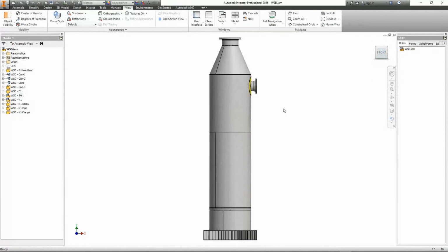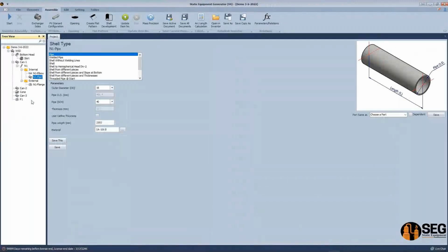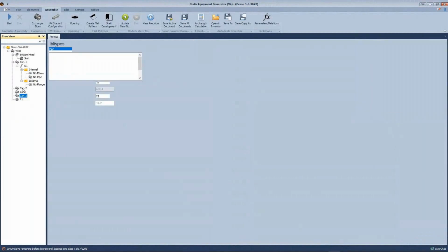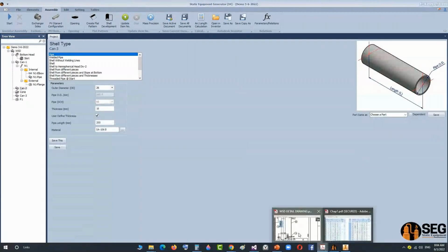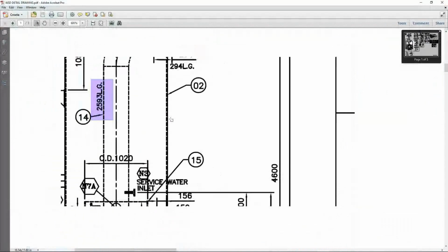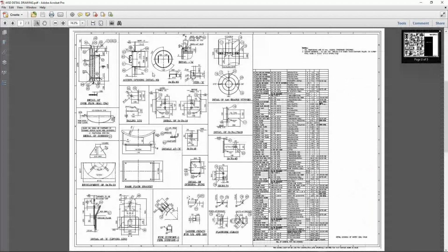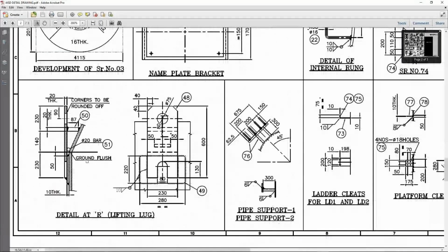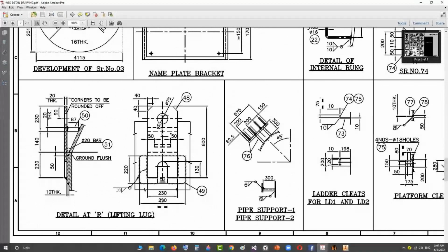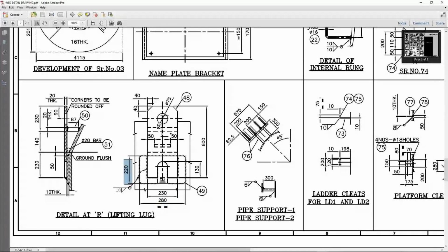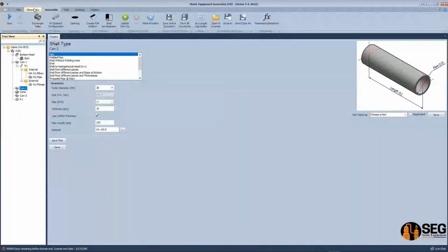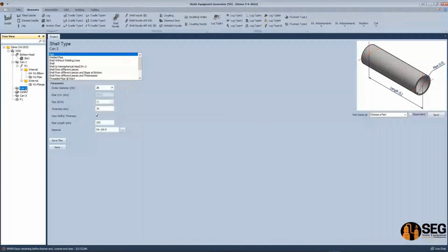Okay, now let's add a lifting lug to this can. So if we come back here, we have lifting lugs, and let's check the detail of the lifting lugs. Here we have this lifting lug. Okay, so that's the width and height. From elements here, let's select the can first, and from here let's add the suitable type for this lifting lug, which is type lug 5.